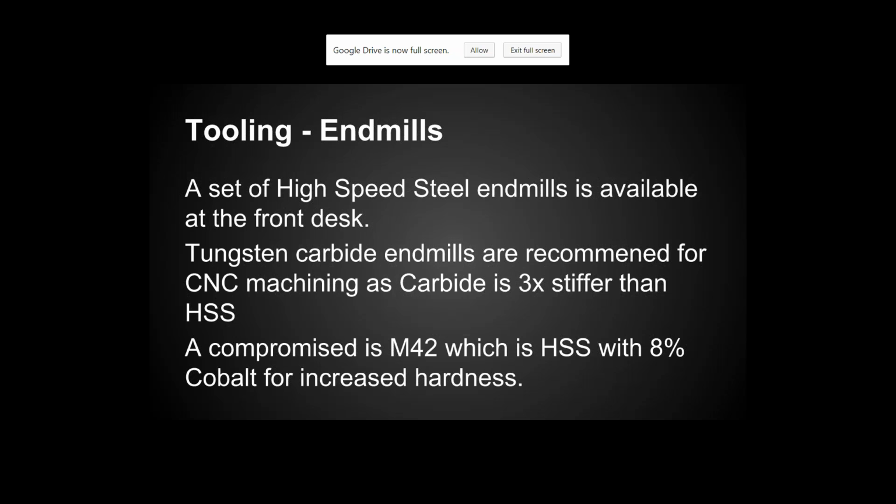So pretty much, let's say if you used high-speed steel end mills up front on stainless steel, I won't say it's an end mill per operation, but it'd be close. Depending on the quality, high-speed steel is just a hair tougher than stainless steel.